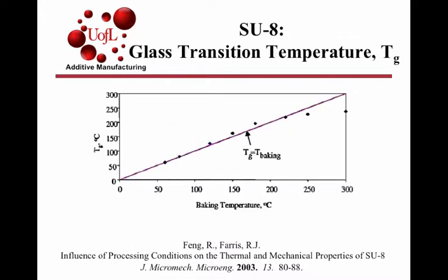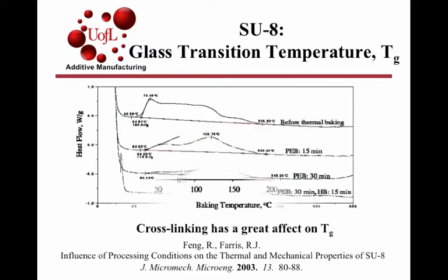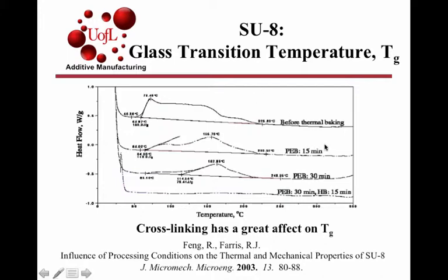What about the glass transition temperature? We said that that could be something that changes with cross-link density. So monitoring the glass transition temperature changes as a function of curing conditions allows us to follow the extent of reaction. And you can see that the glass transition ends up increasing, you end up getting a more brittle material that tracks with the mechanical property changes, and there is a plateauing effect. This glass transition temperature can be measured by differential scanning calorimetry.